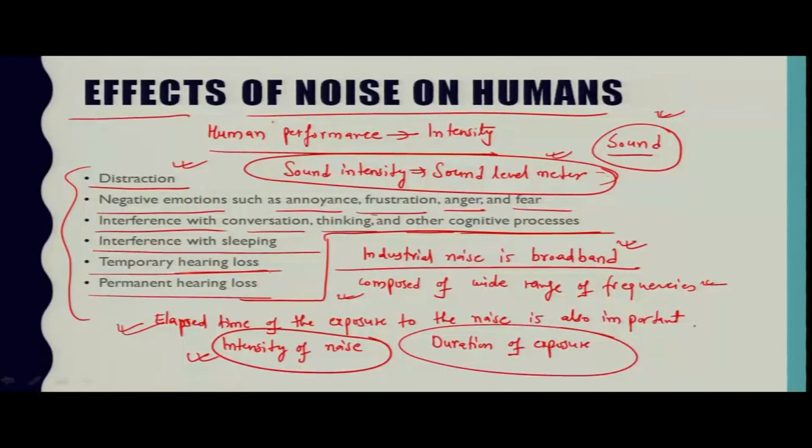Most meters are equipped to allow the user to set one of several different scales when taking a sound pressure measurement. The two most important scales are designated A and C by the American National Standards Institute, ANSI. The difference between A and C is that they electronically weight certain frequencies of the sound pressure signal differently.